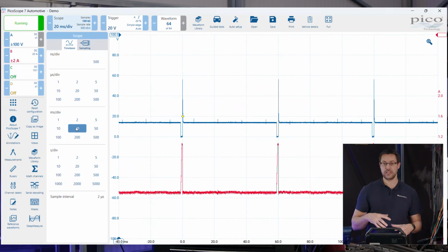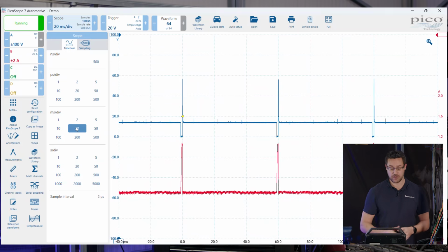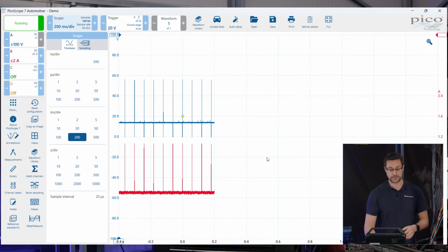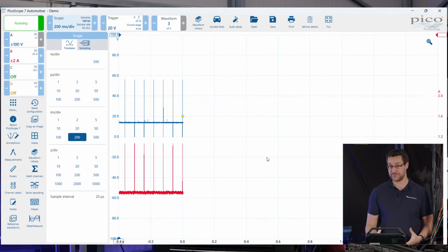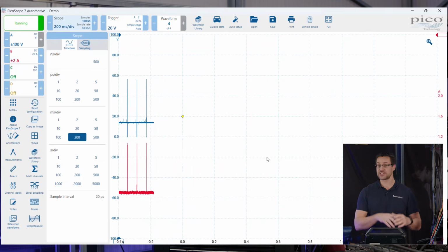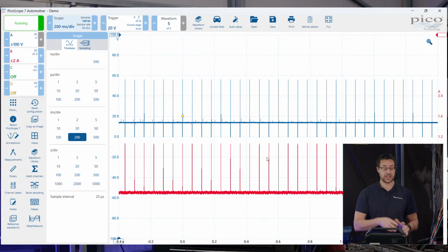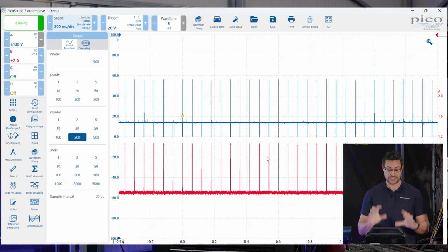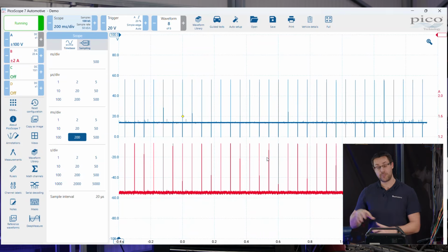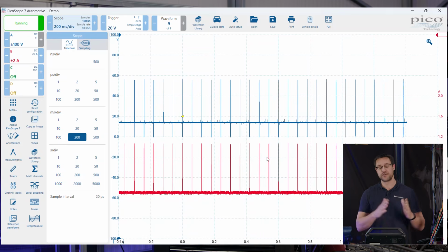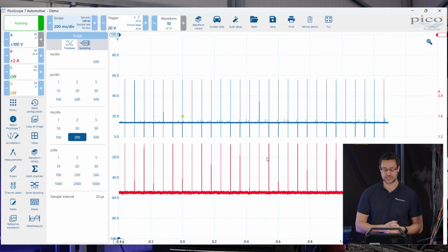Personally, when I'm taking a measurement for the first time, I will always be in streaming. The reason being is that you will always see something. Yeah? Now that's completely up to yourselves. It may be that if we just use the default settings when you start the scope up, we can still get a signal and we can still see it. However, play around with the time base and then obviously you can change the way you see that signal on the screen.